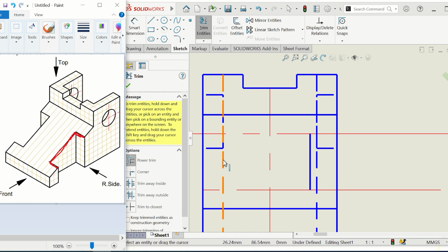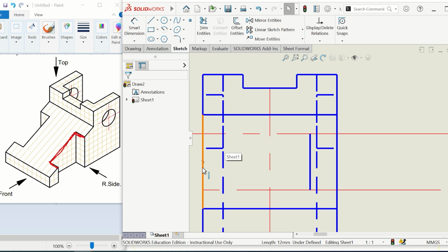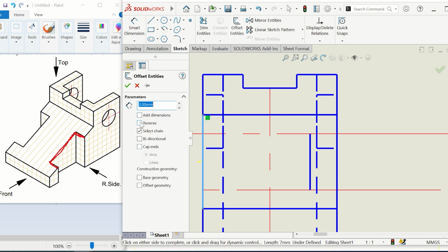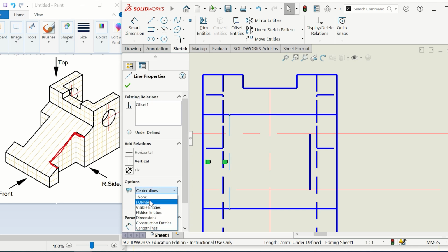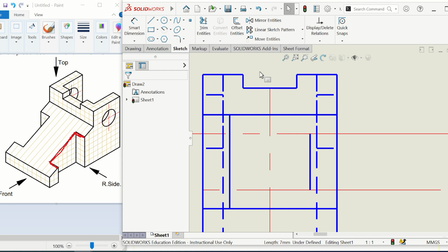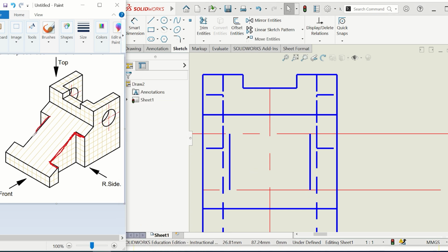Now here I can do the same thing. So let me offset this line, reverse to take it to this side at a distance of 2 units. Oh no, sorry, this line. So I select this line, I go offset 2, reverse it to come to this side because it was to the left, and that's it. Now again I can escape, place it in visible, of course, and I need to trim it from here and from here. So these 2 lines, I have drawn this now.